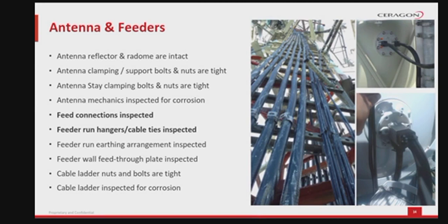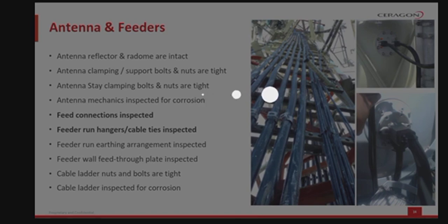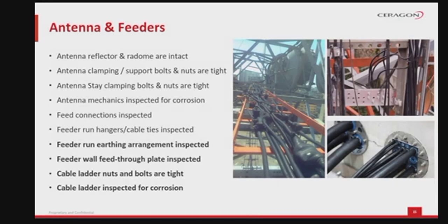For split mount or all outdoor systems, verify attachment of coaxial, optical or Ethernet cables, power cables, and cable ties conditions. In case of all indoor configuration, verify the waveguide hangers and additional fixation components. Perform a revision of the earthing system and verify that all the connections are tightened, no corrosion is present, and the weatherproof system is intact.